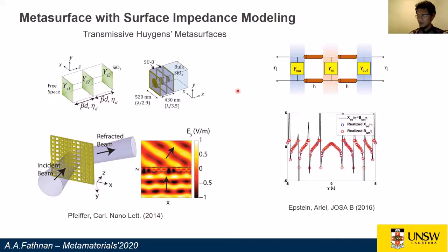In later works, it was shown that shunt admittance or impedance can be solved in a closed-form analytical expression. Therefore, using this surface impedance approach, we can obtain a robust and relatively easy conversion between macro requirements of the metasurface and realistic meta-atom implementations.